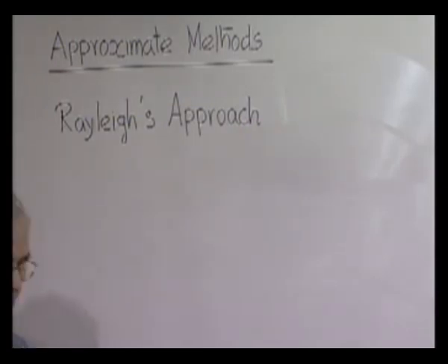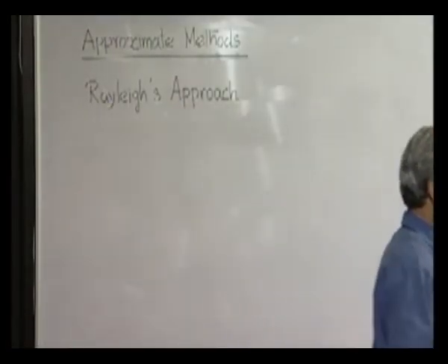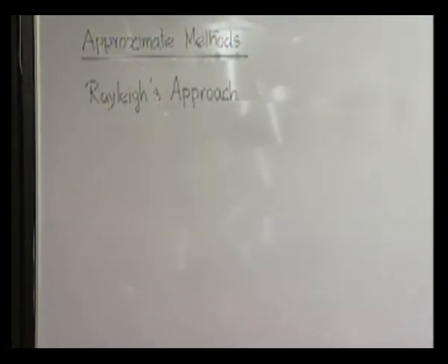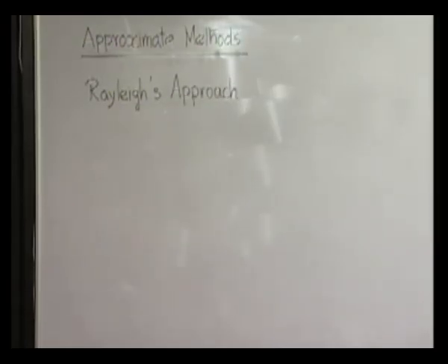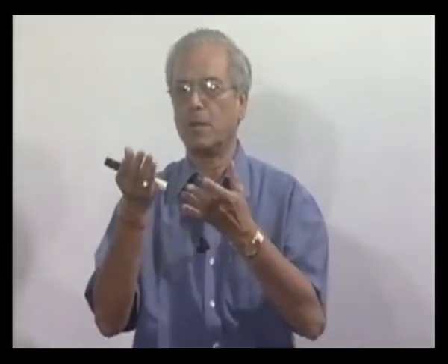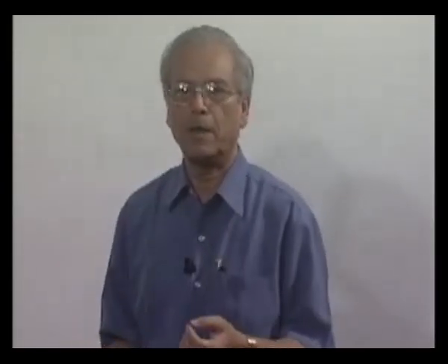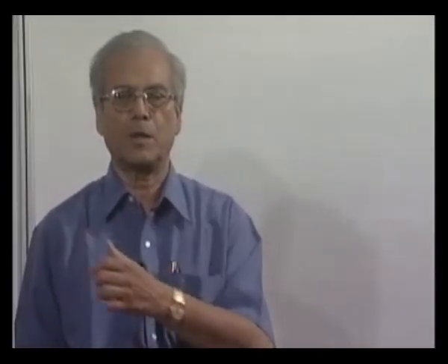We have seen that in Rayleigh's approach for solving free vibration problems without any damping, we considered the condition that in normal mode oscillation all the particles reach their maximum velocity situation or zero velocity situation simultaneously. That means the total energy is in the form of potential energy when all the particles are with zero velocity.